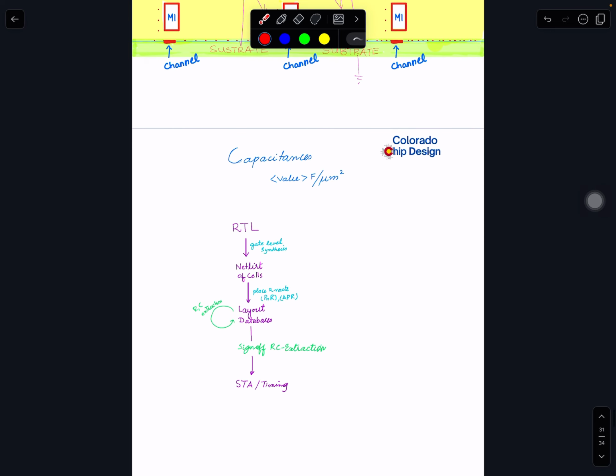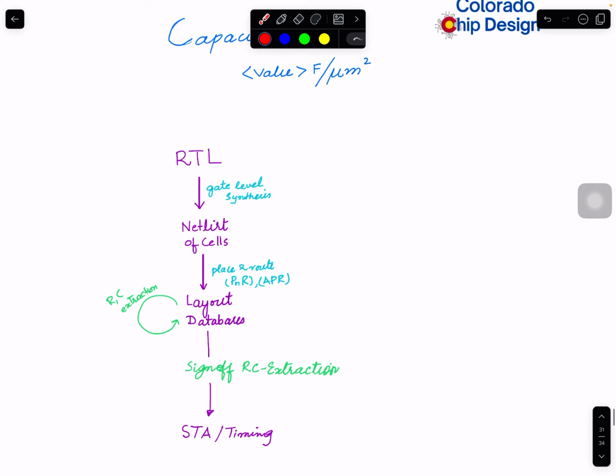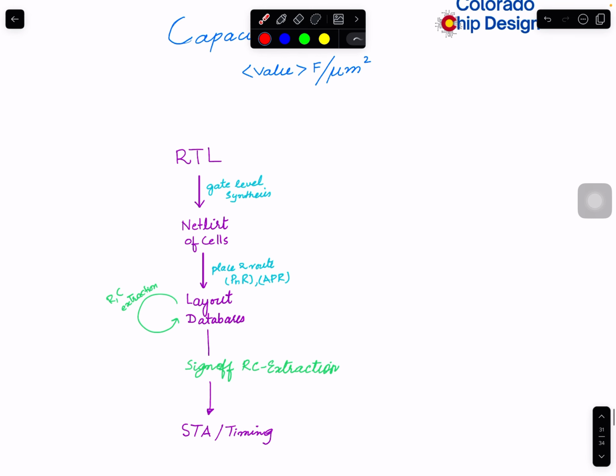So what do we do then? Since this whole course that I'm doing initially is on digital IC design, what we deal with is that we write an RTL. From RTL, we generate a very large netlist. Typically, the blocks that we do are anywhere from 500,000 cells to a million, and I have seen even blocks with 2 million cells in a single block. Those cells are a NAND, NOR. I had videos on combinational circuits where I talked about what a standard cell library is, and I will talk about it again in the physical design series.